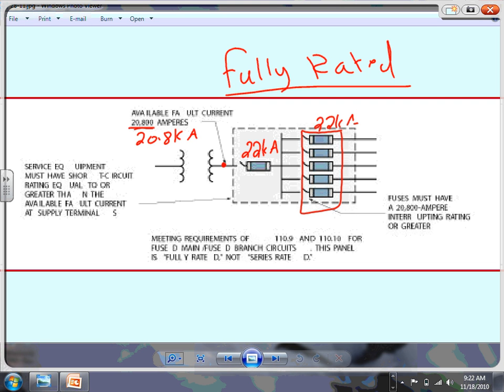What's wrong with this, Brad? Expensive. Now we're not talking about this, we're talking about a 400 amp panel, 600 amp panel, 800 amp panel. You have an 800 amp panel, fully rated, 65K each one of them. Very expensive. So the drawback of this one, and we will come and visit it, is that it's expensive for your application.